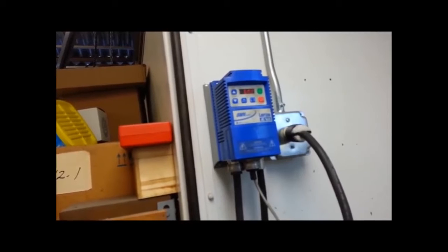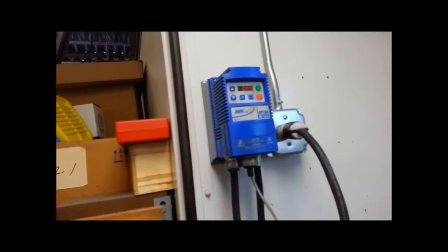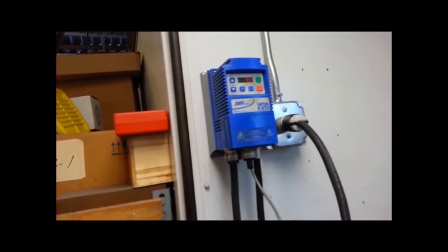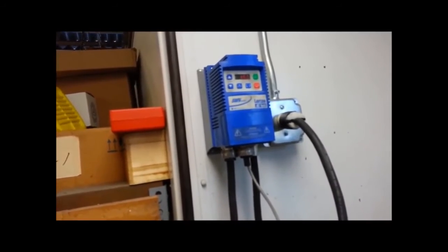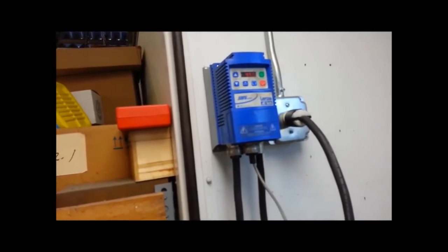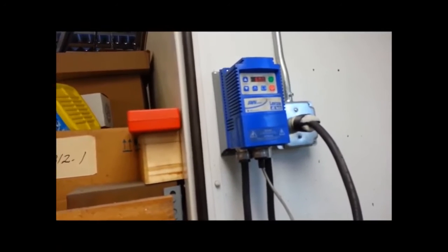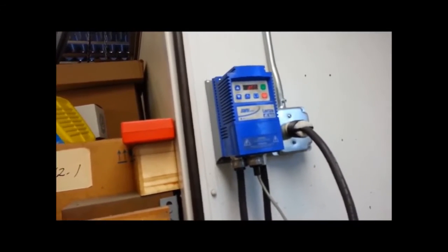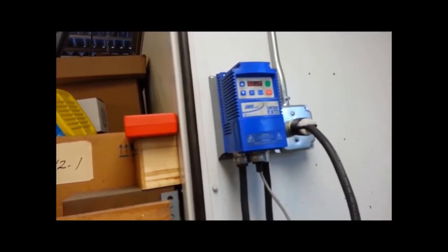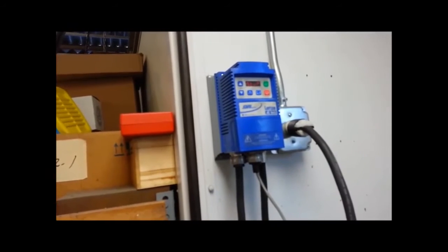Now if I just take this thing and cram it all the way through stop and all the way over to reverse, I'll show you what it does. It decelerates, goes to 0, and then it ramps back up. It's not going to give a forward or a reverse run command until the motor has come to a complete stop. So the unit is smart enough to turn itself off and come all the way to a stop before applying the run command in the opposite direction.